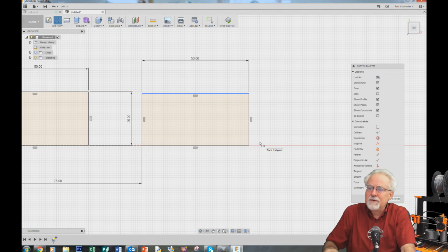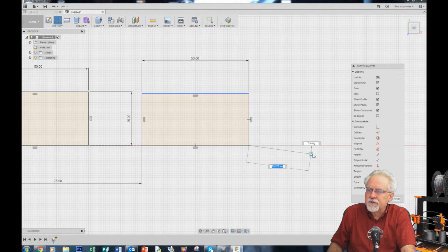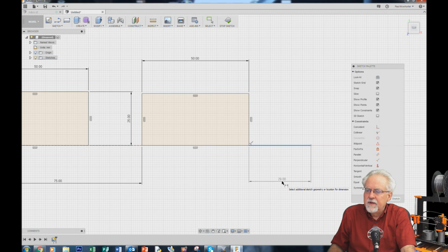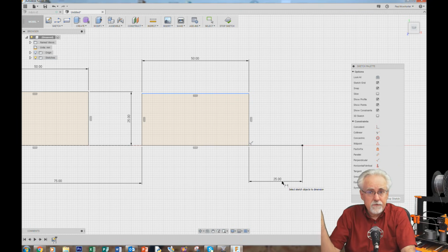So I'm going to say line, L for line. I click here. Make sure that you're staying snapped to the grid. Do you see how it wants to snap to the grid? Make sure that you're snapped here, and then I click again. And now what do I do? Dimension. So D for dimension. I click this, I come down. This dimension I want to be what? 25.